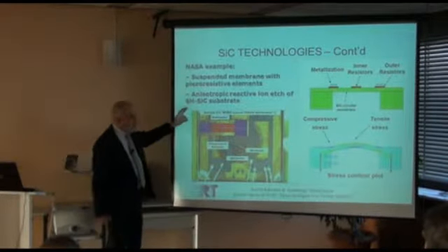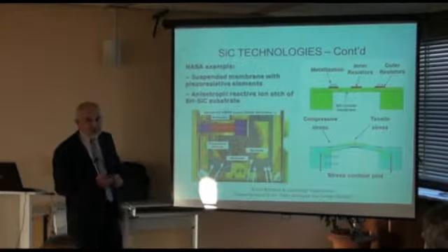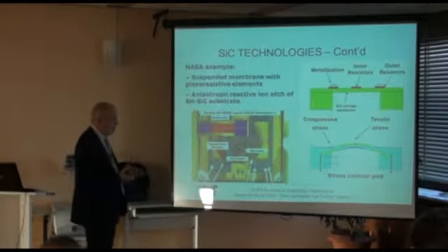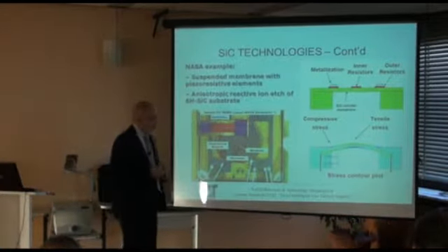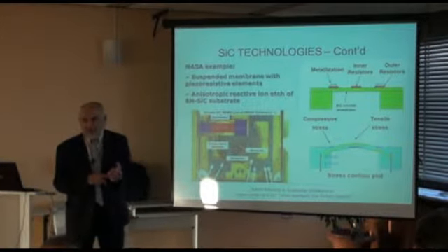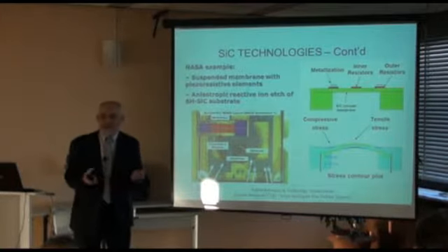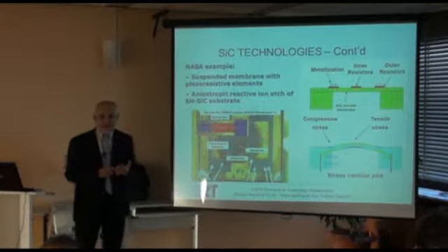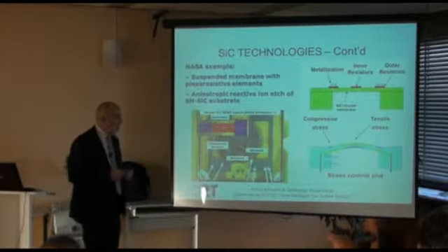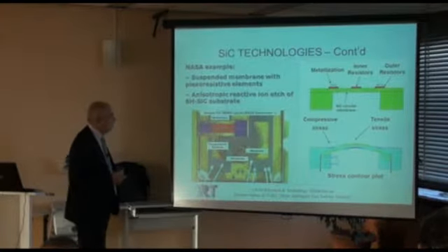Now, issues would be how one works with silicon carbide. That is one of the issues. Silicon carbide requires a special type of technology to be etched. It's not etched like silicon. Silicon could be etched either wet, in chemical liquid state, or with gases. And gases are the most accurate etching, but definitely they are not environmentally friendly, and quite expensive.